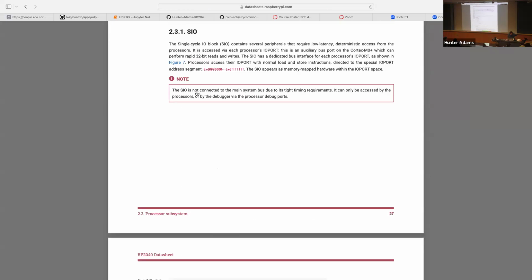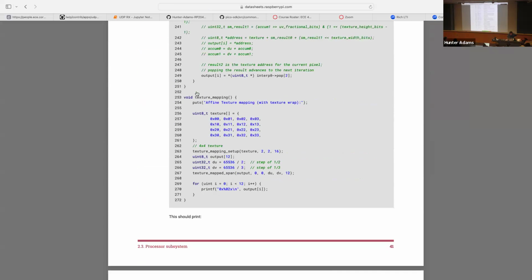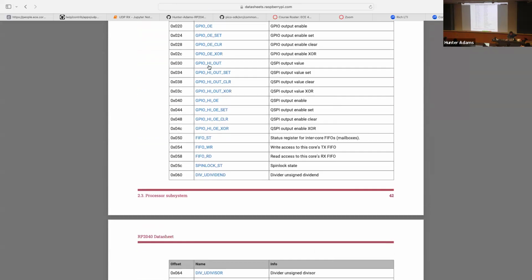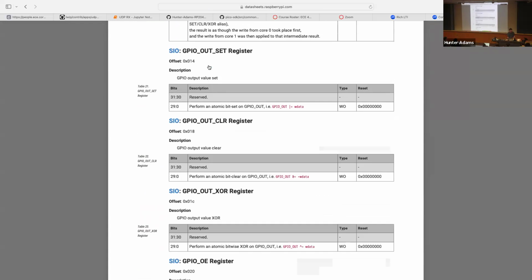And we could look down at our registers and look at the appropriate offset address. It was hex 14. And learn more about that particular register that that particular C function is touching. And what we noticed is this particular one, when we write to it, it does an atomic bit set of the GPIO out register. So it sets the GPIO outputs.